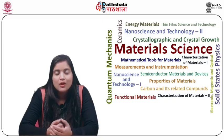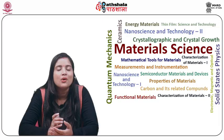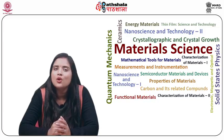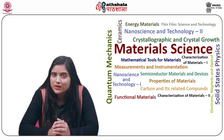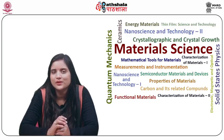Electroless plating is a versatile technique to produce a broad range of coatings. Most popular industrial coatings include low phosphorus, which is hard. This bath is used to deposit coatings having hardness around 60 Rockwell.